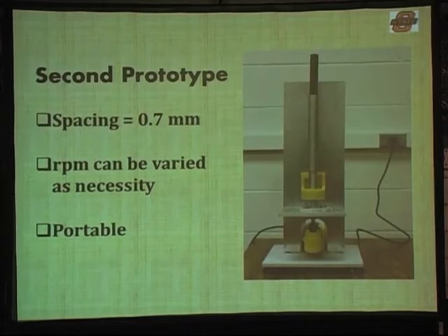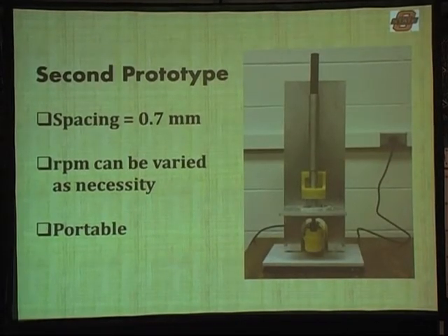This drill, a DeWalt drill, can get up to about 1200 RPM, so a little bit less. But we've actually tested this as well, and since the RPM is a little lower, we can get to on the order of about 140 C in this case. And this just has a simple plunger, feed some in, push it through.